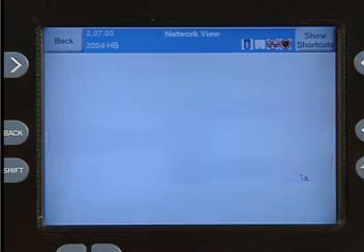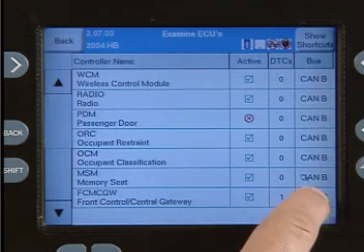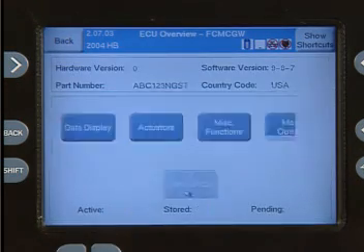Earlier, we discussed some of the symptoms you might find in cases of partial or complete lack of communication on the buses. Because of the way components are integrated into a CAN bus system, these symptoms may or may not point to a cause. That's why it's important to use the StarScan to determine the status of bus components. And when you have retrieved diagnostic information, such as diagnostic trouble codes, it's important to use the published procedures to investigate the cause.